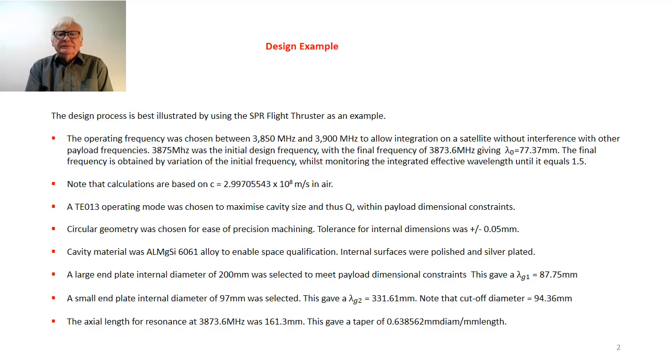The actual final frequency, as I've said before, is obtained by variation during the design process, and we vary that input frequency whilst monitoring the integrated effective wavelength over the cavity axial length until it equaled 1.5, in fact 3 half wavelengths.